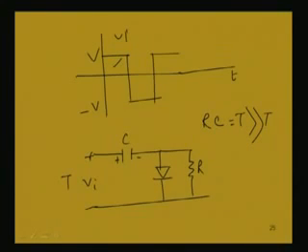This is an ideal diode, there is no drop, and it will be like a short circuit, conducting through this part. So, this capacitance will be charged to a voltage of V, and as the discharging time constant is almost 0, because the diode has a very negligible resistance, and in this case we have neglected that resistance. So, the charging time is almost 0, and instantly it will be charged to a positive voltage V, the peak value.